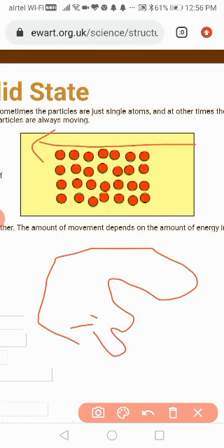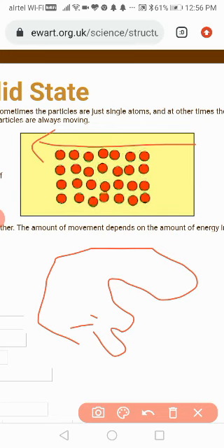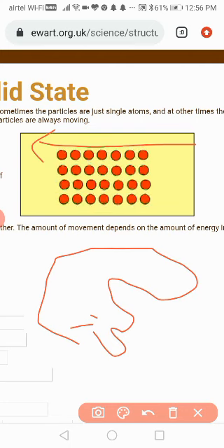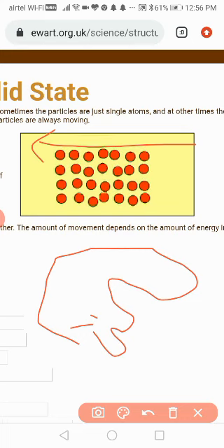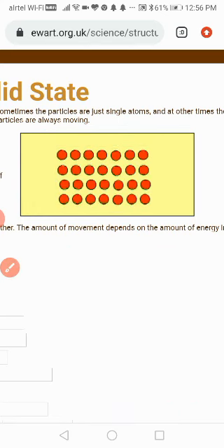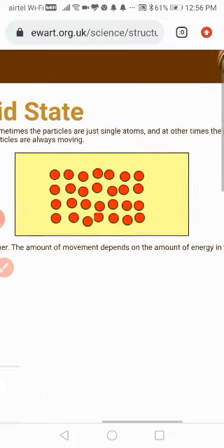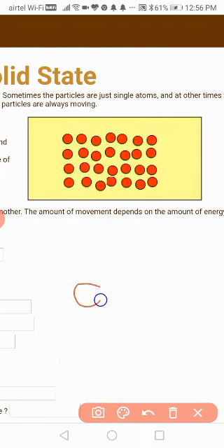The electrons which were supposed to move freely are getting more collisions, and the effect of the electric field is decreasing because thermal velocity is increased, as we have already discussed in the previous lecture. The thermal velocity and the velocity imparted by the electric field. But as we have seen, the increment of temperature will increase the thermal velocity. So if the electron is there, there are two kinds of velocity it has.